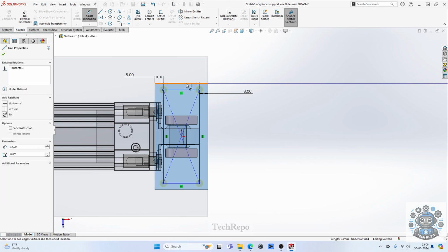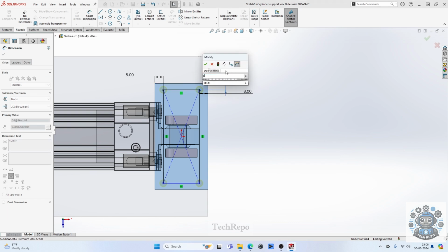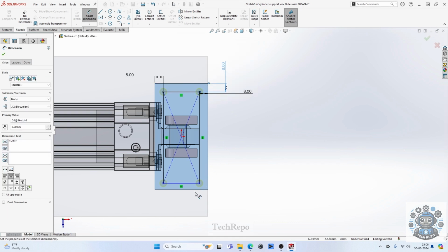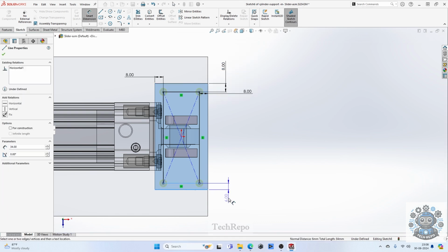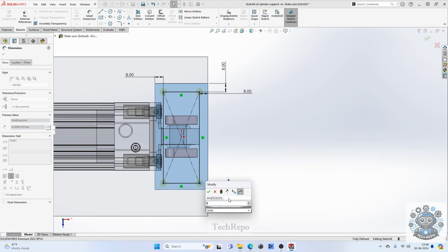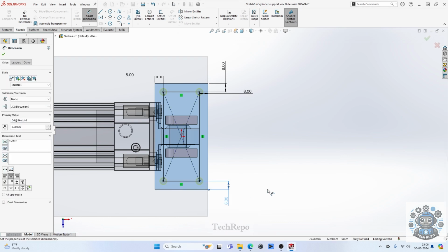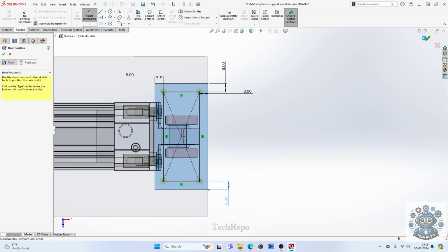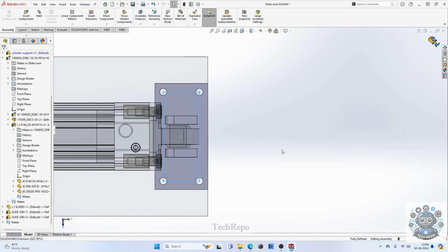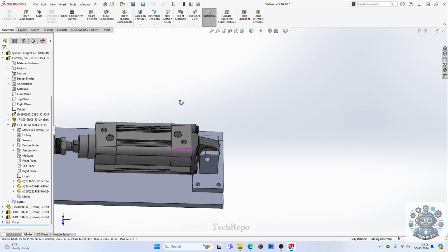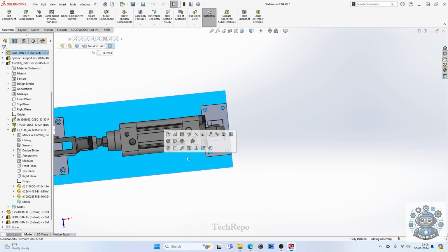Like I said, for the rocker assembly in the front you may not need M6 because it's not going to be affected by the load, so you can go with M4 also, but we would prefer to stick with M6 because on the mounting side you will definitely need M6. So now this hole is defined.